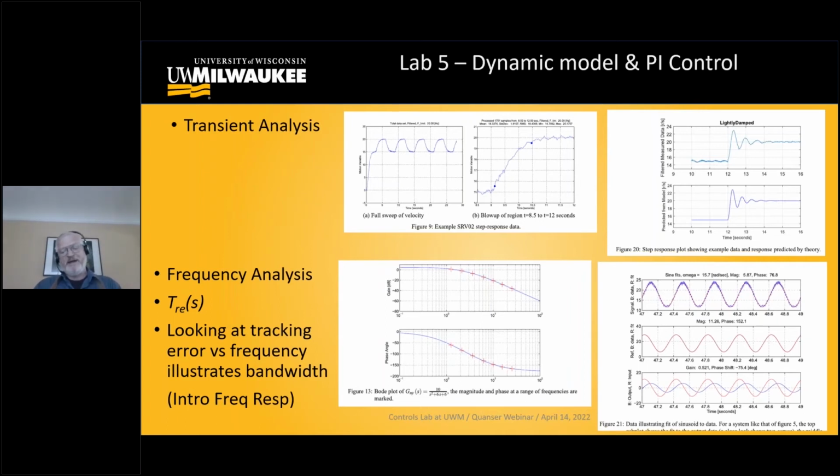And again, system identification is this long-running thread in the sequence of labs where they start with a very basic model that incorporates DC gain. At this point, lab 5, they're working with a model that brings in that first order transient of the motor servo, and then we're going to progress to a more elaborate model identified with frequency analysis methods.